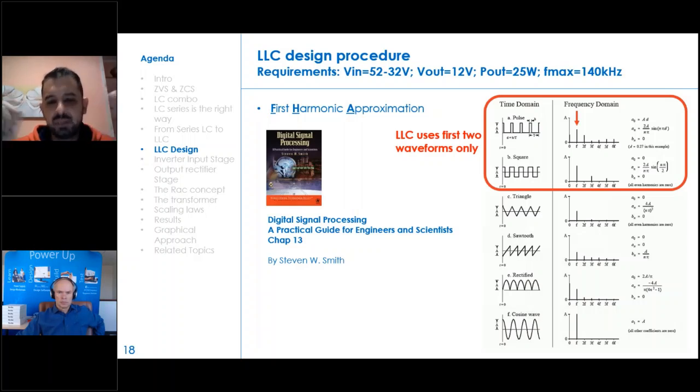a non-sinusoidal signal, let's say a square wave, triangle wave, sawtooth wave, and so on, an approximate solution can be evaluated by sourcing the same circuit with a sinusoid having a frequency equal to the original frequency, and an amplitude equal to the one you get by using the Fourier transform of the original signal, the Fourier transform, obviously, of the non-sinusoidal source.